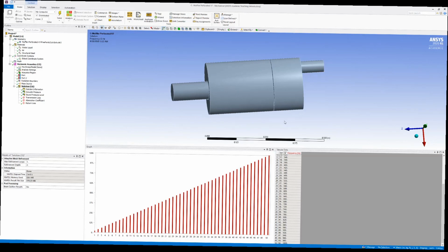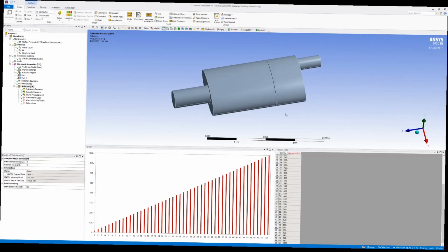And with this acoustic analysis, you can also optimize for Helmholtz resonance so that your sound waves propagate at the nominal frequency bands that would encourage and optimize the amount of engine breathing through your exhaust and essentially help you produce more power out of your engine.